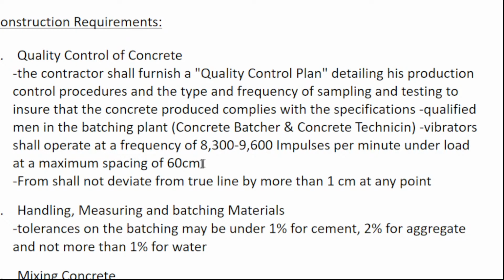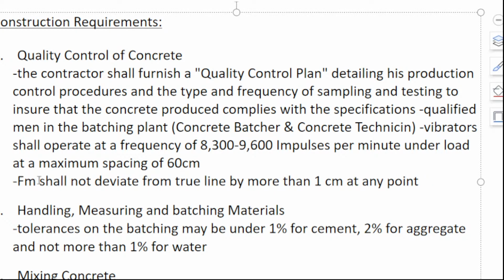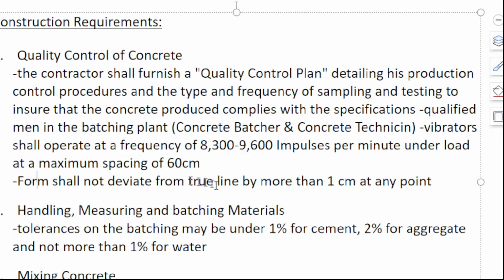Okay, so this is a requirement so that we do not have honeycomb, to avoid honeycomb. Okay. Form shall not deviate. So this is another typo error. This is form. Shall not deviate from true line by more than 1 centimeter at any point.